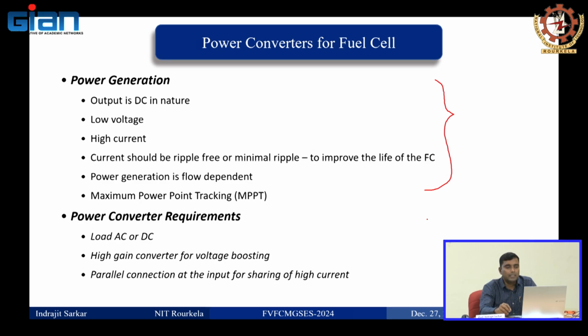But the thing is, as I mentioned, this voltage is low. This voltage is 33 volt, and at home the voltage that you need is 230 volt RMS. So how we can convert them? You have to first boost the voltage. Boost converter. Yes, absolutely correct. Boost converters: step up the DC voltage and then convert into AC. Now the thing is, here the voltage is 30 volt or 33 volt, and you need a voltage level of around 400 volt.